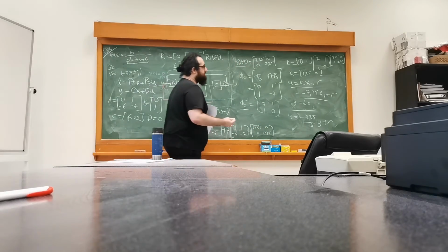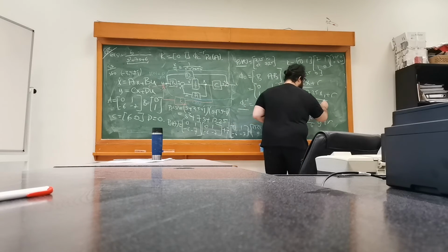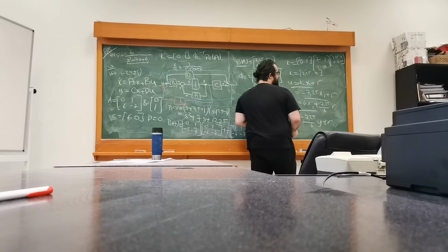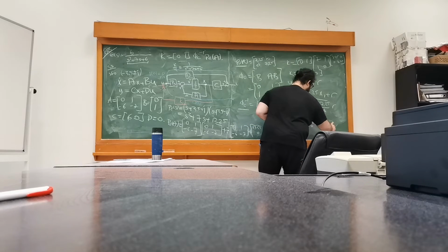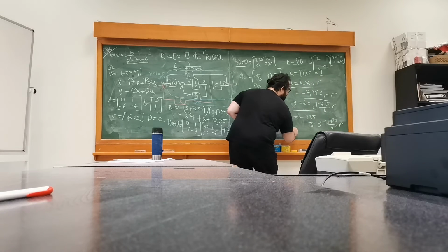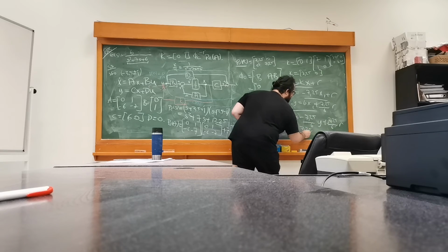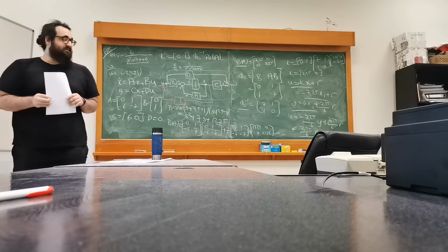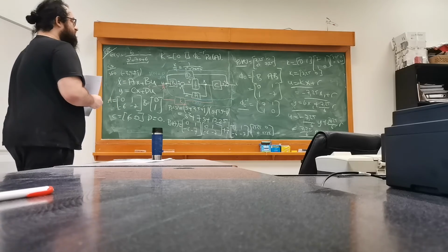Well, if I'm fancy, what I can do is I can just add 7.25 divided by 6 times r as a feedback law, and you can immediately see that r minus y pops up. 7.25 divided by 6 e would be then the feedback law. This would correspond to a p-type control. It doesn't have to be. It was a special case.